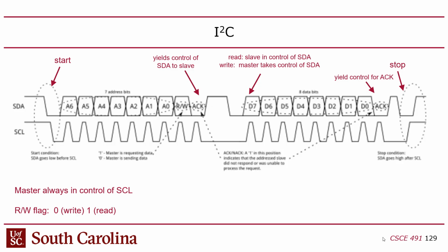And so the I2C protocol understands that. That's called clock stretching. Clock stretching, yes, sorry, couldn't remember the term. That's where the slave can control the clock, but only under this case where it wants to delay things, right? Normally it doesn't do that, but it's an option, right?